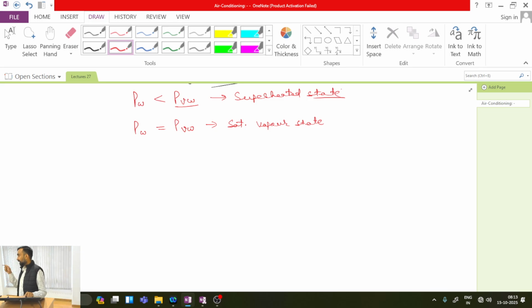Okay. So in that scenario, if I start cooling, immediately the vapor will start condensing, because whenever we decrease the temperature, the moisture carrying capacity of that particular gas decreases. Okay, the moisture carrying capacity of the air will be decreasing. Why will it be decreasing? Because with decrease in temperature, the corresponding saturation pressure or vapor pressure will be decreasing. So in order to decrease the vapor pressure, some of the vapor molecules have to condense into liquid. Is this point clear?